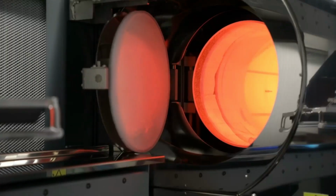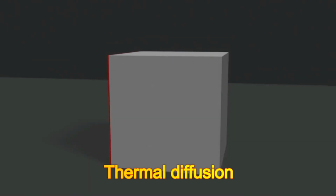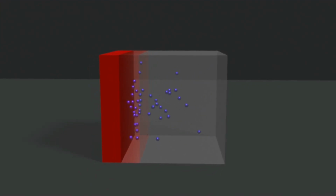The process described here is known as thermal diffusion, which remains one of the most widely used industrial methods for forming doped regions in photovoltaic manufacturing. In this technique, as described earlier, wafers are exposed to phosphorus-containing gases at high temperature, allowing phosphorus atoms to slowly diffuse into the silicon surface.